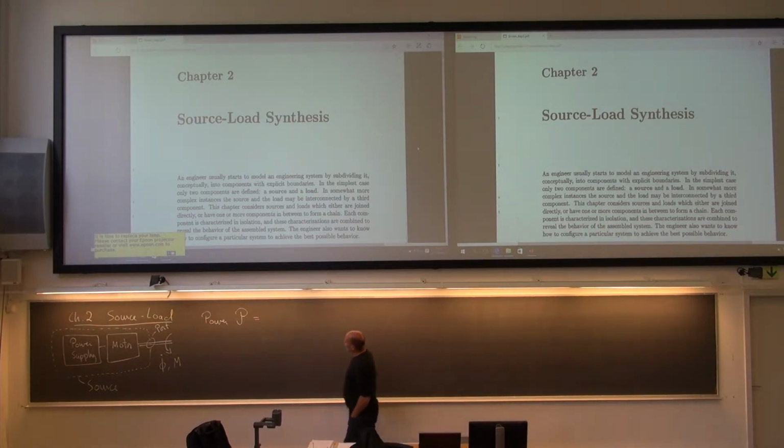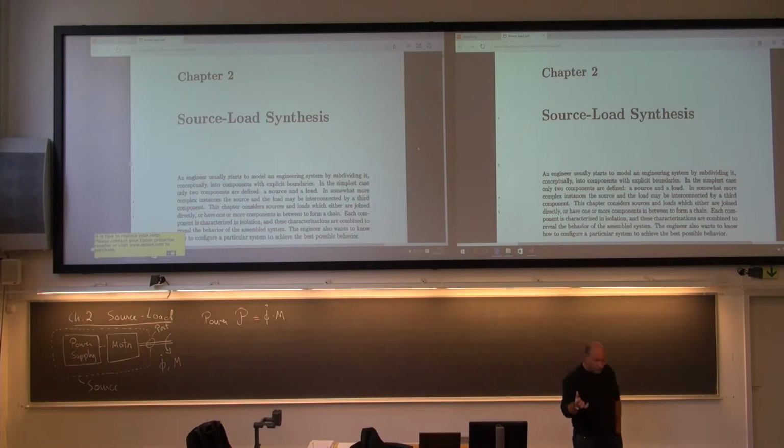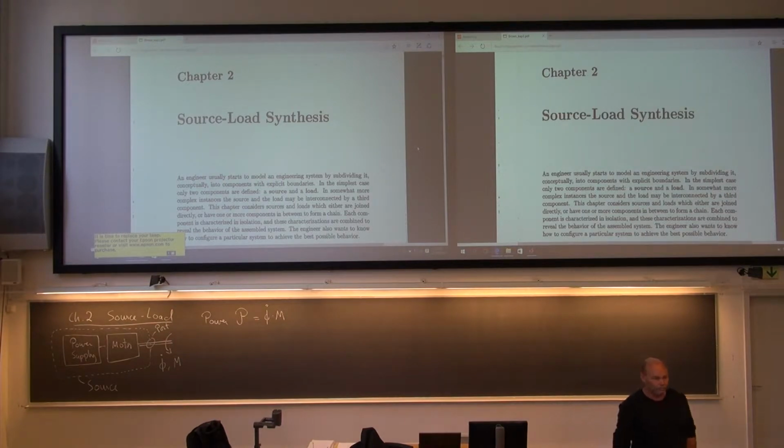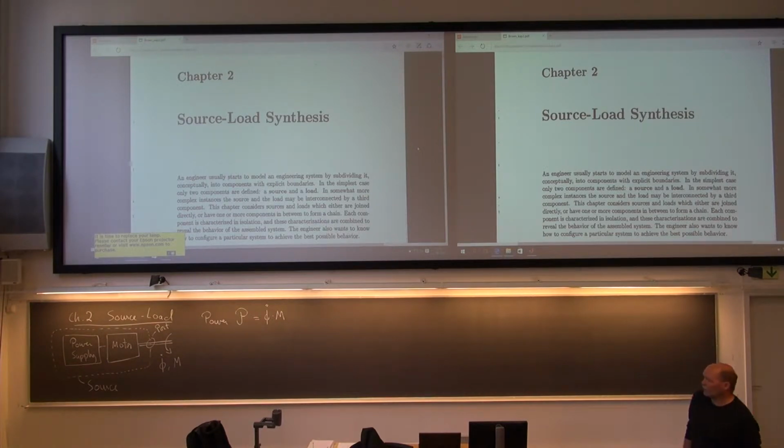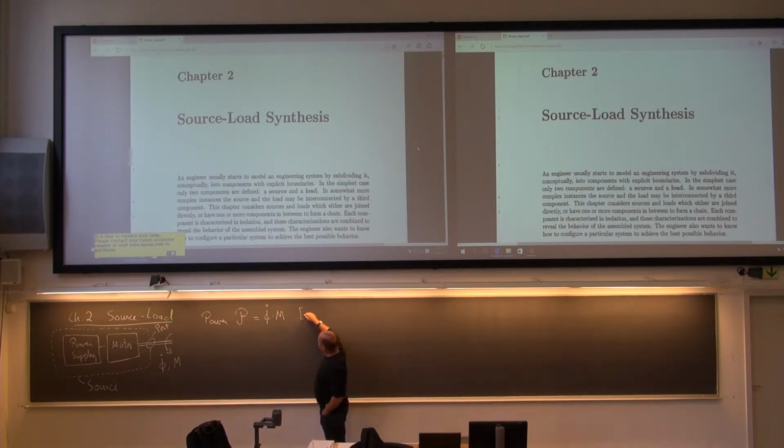Well, you simply multiply these two together. So in order to actually do something, to do some work here, you need both rotational speed and torque. Just one of them doesn't do anything for you, but the combination, okay, then we are talking power. And here we dimension watt.